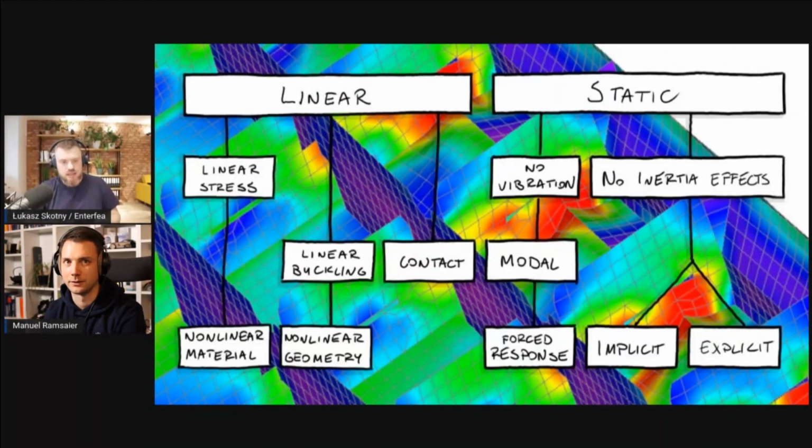So in the end, you have something like an ideal model, and imperfections for dynamic analysis would be crazily more complicated than for buckling analysis. Because for buckling, you need just the shape that kind of follows how the thing will buckle. That's more or less easy. Imagine that even if you would just bend the sticks and look at them, you could kind of imagine how this will look in real life.